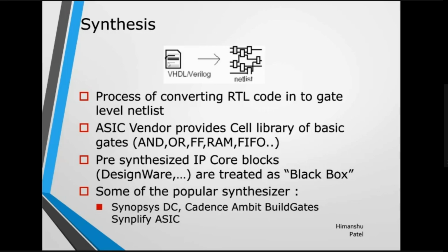The tool has syntaxes where you can tell it that this is an IP and a black box module. So consider it as a black box module, and I will give you the library for this particular full adder without the functional logic. Only I will give you input and output ports. So treat it as a black box and proceed with the processing further. That is how it is done when you have a pre-synthesized IP. We'll learn more on black boxes and IP when we do the labs.